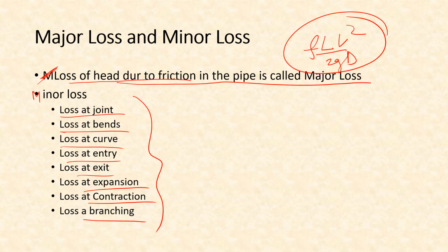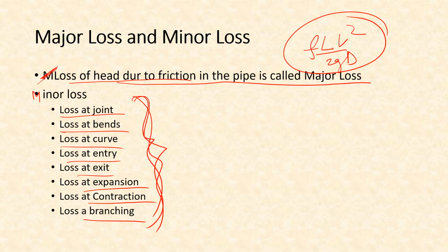One of the problems, you can choose whatever problem you want, then you can try calculating the head loss or the velocity, and see if you ignore these minor losses, how much difference it will make. We'll see that if the pipe length is very large, that means we are dealing with pipe lengths of hundreds of meters or kilometers, the minor losses are almost insignificant. But if you have a very short pipe length, the head loss due to the minor losses will constitute a significant portion of the head loss.